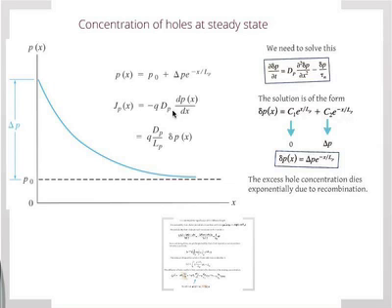And minus q, just because, recall, they go from high concentration to low concentration. So dp over dx is negative, right? Because it's decreasing. So you have to have the negative sign because it's in the direction of the decreasing concentration. We talked about this last class, so make sure you're pretty clear about that. And you can plug everything in, you get an equation that looks like that. So now you see that the current is also exponentially decreasing with position.